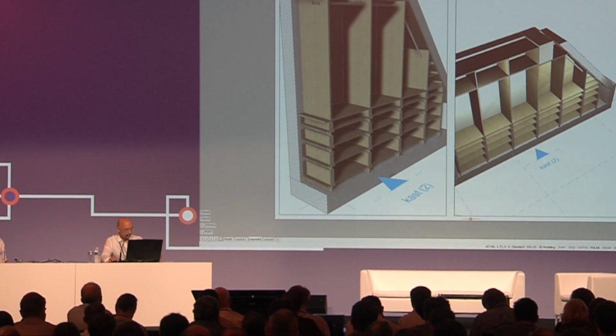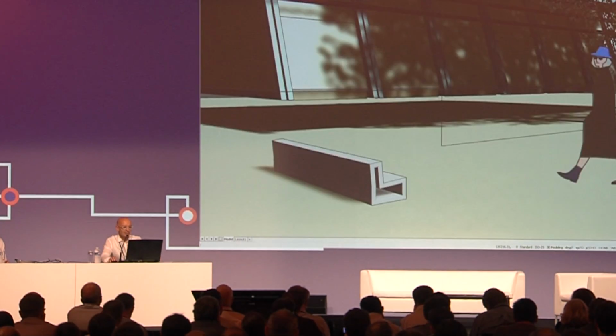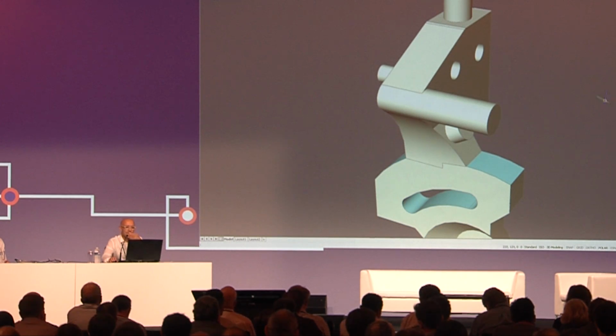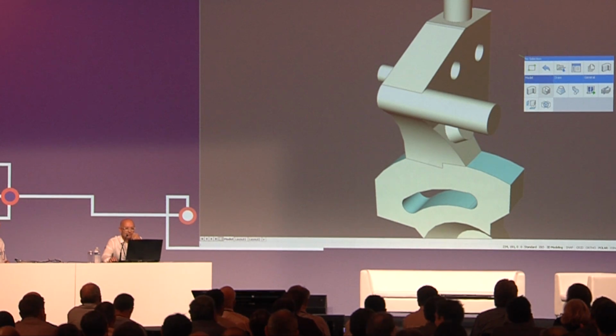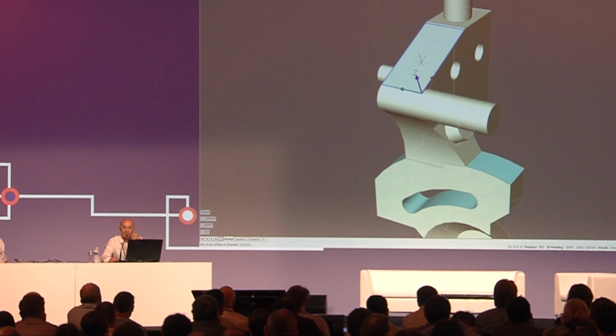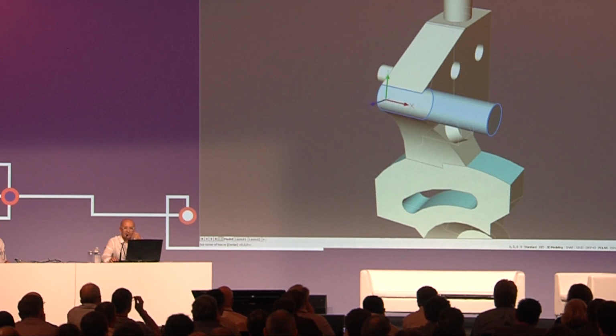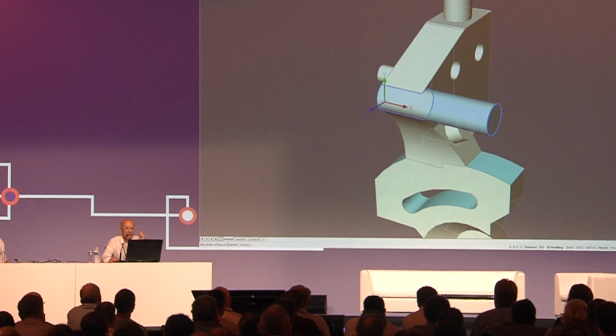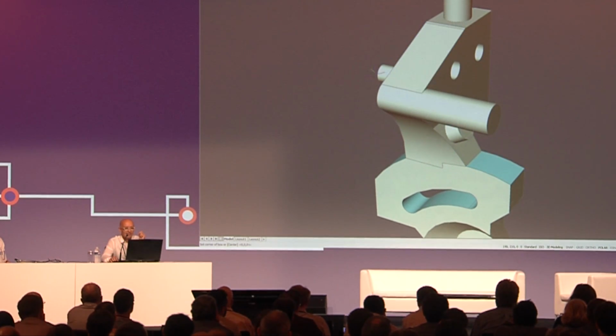Now, talking about ease of use and giving comfort while modeling, let's see how hard it would be if I wanted to model a slab. And I want this slab to be parallel with this face. Now look what happens. I started the slab command, and you see dynamically, you see this cursor go. It indicates your user coordinate system, and it's a dynamic one. And if I hover over another face, you will see it go along dynamically. And once I decide that it's in a good location, then I can lock it in BricsCAD.